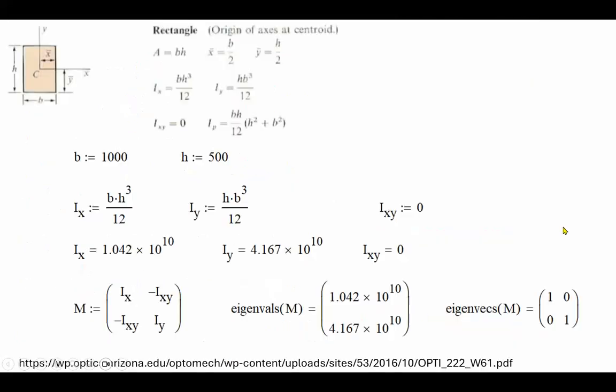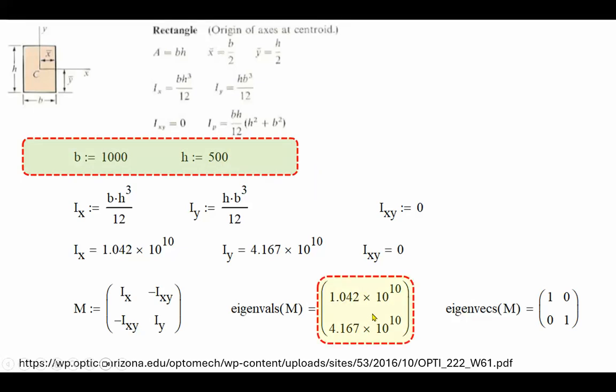As a second example, I will be using a rectangle, and the information for the moment of inertia, or moment of area, with respect to x and y axis, are given there. Obviously, in this case, because of symmetry, Ixy will be 0 right there. I'll be using a rectangle of dimension 1000 millimeter by 500 millimeter, and I should be getting these numbers. Incidentally, this second example, I will do as a padded object, and I select the top face of it so that it's not a surface. For the first one, I'll do a surface. Okay. All right, let's go ahead and do that.